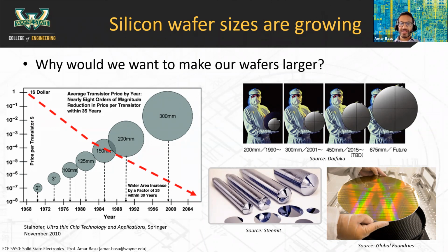Yeah, exactly. You hit the nail right on the head. Yeah, thank you, Corey. This is exactly it. This is what's called a batch fabrication process. We're not making transistors one at a time. We're making transistors literally almost trillions at a time. The same 200-step process can be used to make a single transistor or 10 transistors or a trillion transistors. The same 200-some steps. Okay, so why not just make a whole bunch of them at the same time?